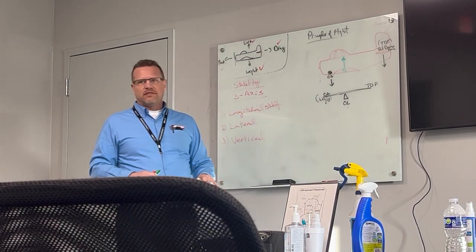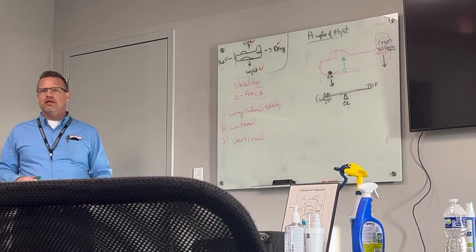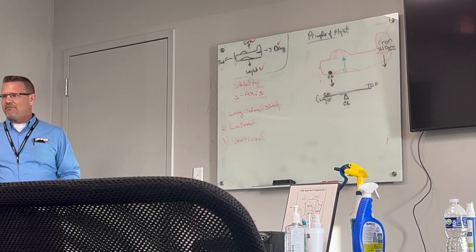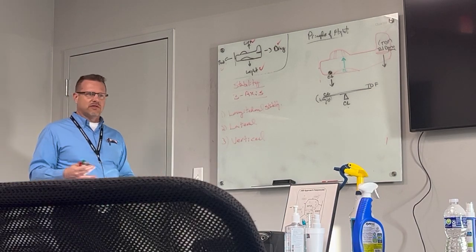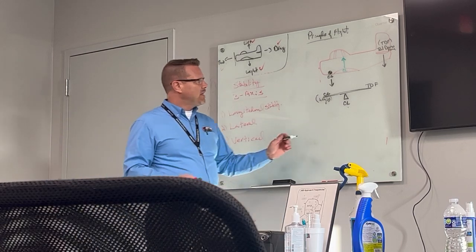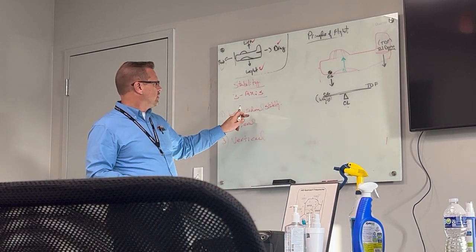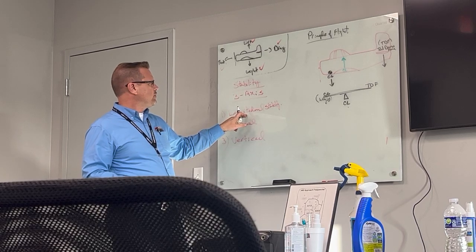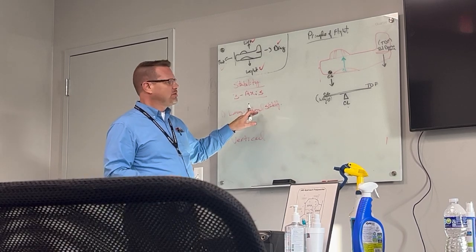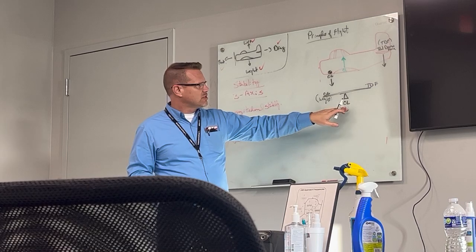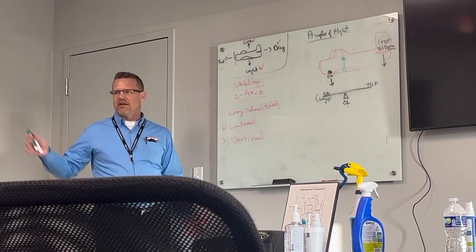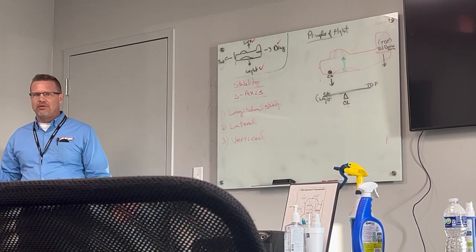Our center of lift, does that change? Well, it does, depending on, just like we discussed, how fast we're flying, angle of attack. There are different things that control lift. But it really doesn't matter in this example for our longitudinal stability, because our center of lift is literally our fulcrum. It's what everything is operating around.